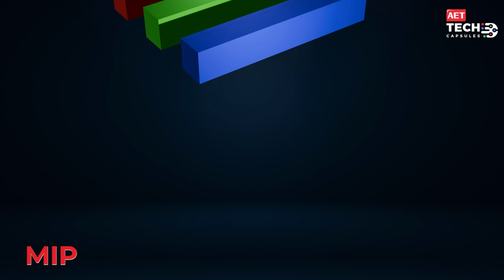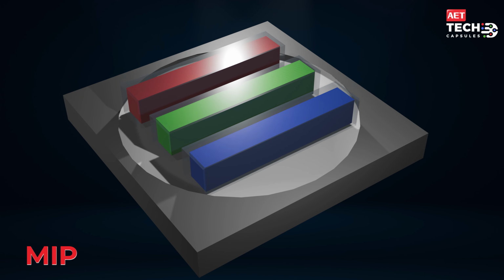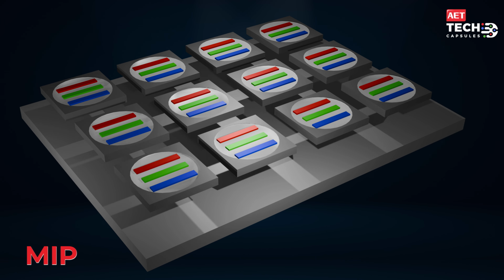To get out of that, a new technology was invented, which was MIP. Now in MIP, what has to be done? The individual red, blue and green chips were packaged in one single package, and then these packages were again transferred the same way COB is done. So the possibility of color merger was reduced.